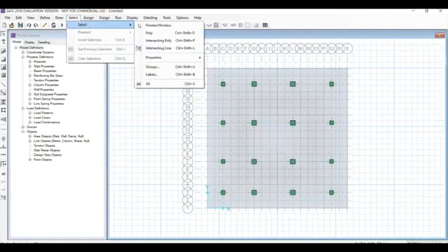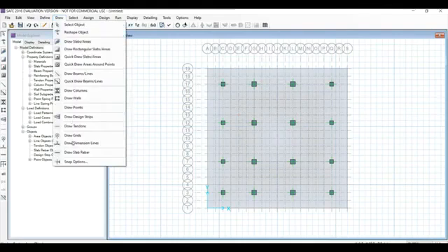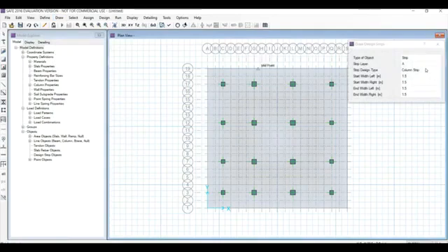Go for the select contributor. And now we need to draw the strip lines. So for that, draw design strips. Our least dimension is 18 meters, and we need to have at least 0.25 times the least dimension, and 0.25 times 18 is 1/4 of 18, 4.5. So start with 4.5, and again 4.5, 4.5, and 4.5. And now strip layer A and column strip.